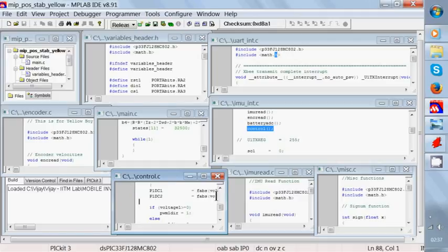after the voltages are saturated, in order to avoid excess voltage being applied, which is also not possible, and it's a logical error. Hence the voltages are saturated to the peak value. It's the maximum duty cycle of the register, and it's loaded into the duty cycle register.